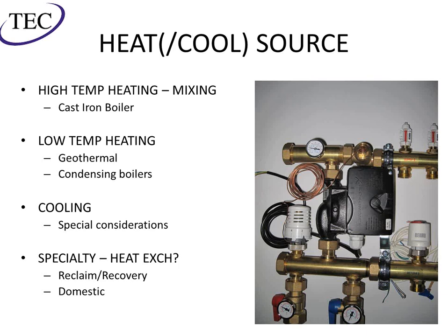And then there may be some specialty applications where you're using the heat reclaim from a chiller, or you have a small basement zone where it's not worth installing a boiler, so you're just going to run off the side of a water heater, with or without a heat exchanger. So there's a lot of different applications, but you need to make sure that you have a viable heating or cooling source, or they're willing to install one.